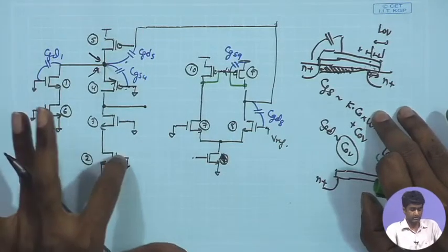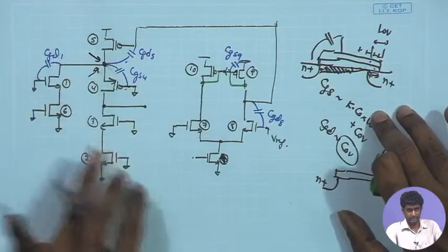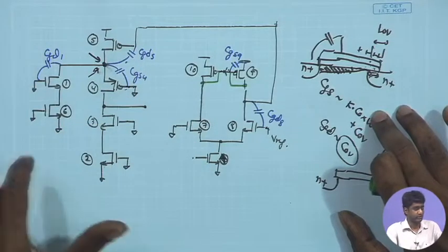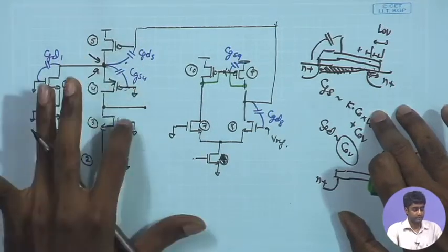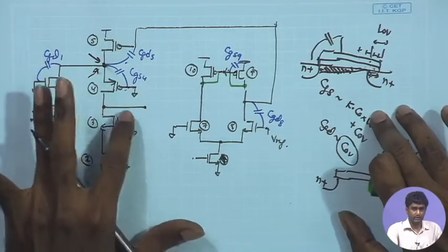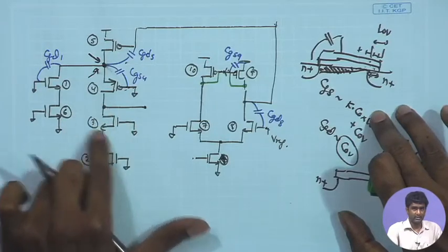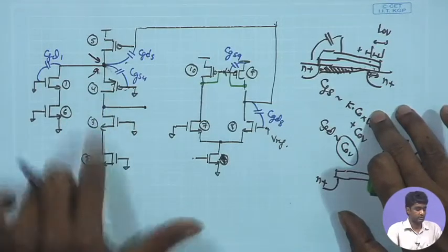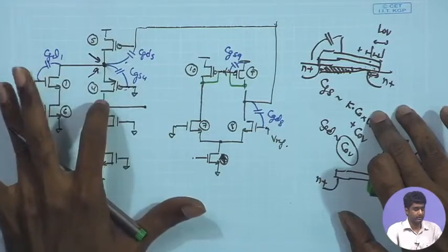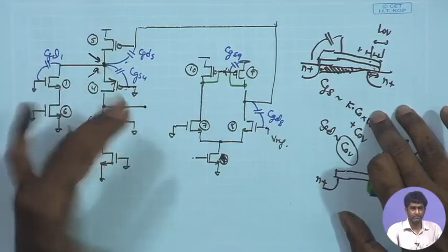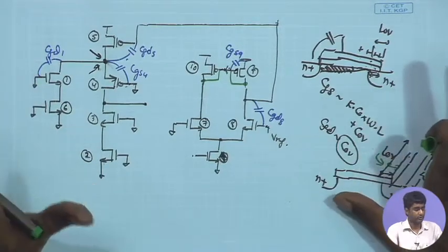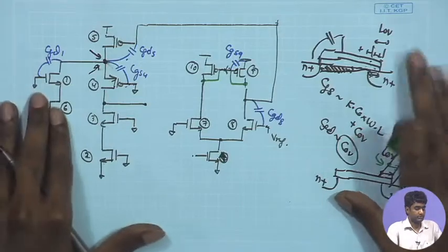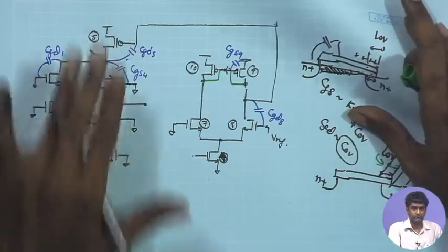We have to remember that the gate potentials of the other 4 transistors are anyway constant, so they are DC bias points, and we have to apply the MOSFET noise, that is the flicker noise at the gate, and the channel current noise in parallel with the channel current source of the MOSFET, and then arrive at the final output noise expression divided by the overall amplifier gain to arrive at the input referred noise at the input point. That is what we are going to do in brief. So, let us do that and confirm the contribution of these transistors in determining the input referred noise.